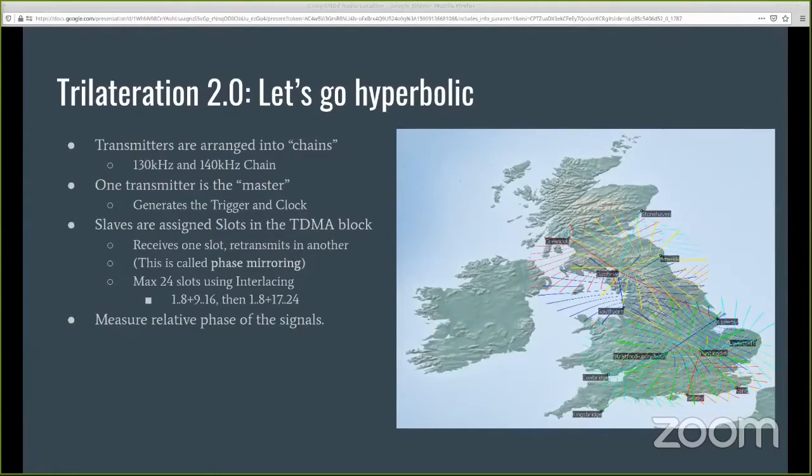And what that gives you is the same thing it gives you in the G... sorry, I've forgotten the name of the thing. Decca and similar hyperbolic navigation systems. So between the transmitters you have a straight line, which is the line of position, the baseline. And the little curved lines are the hyperbolic lines of position. So what you can see there is that they repeat roughly every half wave.